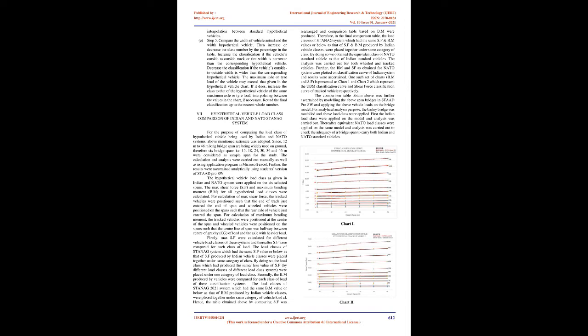The calculation and analysis were carried out manually as well as using an application program in Microsoft Excel. Further, the results were ascertained analytically using the students' version of STAAD.Pro software. The hypothetical vehicle load classes as given in the Indian and NATO systems were applied on the 6 selected spans. The maximum shear force, SF, and maximum bending moment, BM, for all hypothetical load classes were calculated.